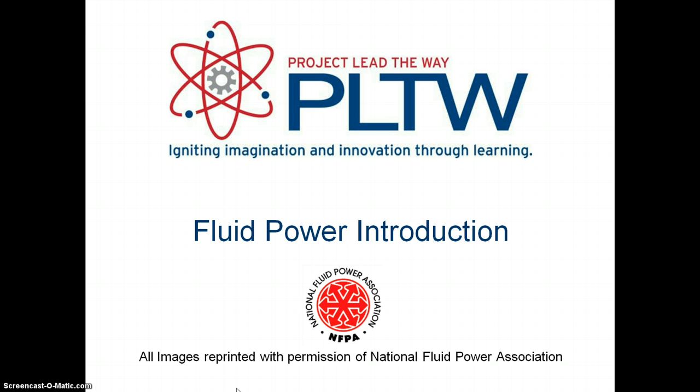Fluid power possesses some really important characteristics that we need to learn about. Fluid power has a lot of power per unit volume or mass. This is usually called power density. Fluid power systems are able to multiply force. And another advantage is that fluid can change direction quickly without damaging the system. This allows engineers and designers to utilize flexible piping and hoses so they can transfer liquid in a variety of directions.